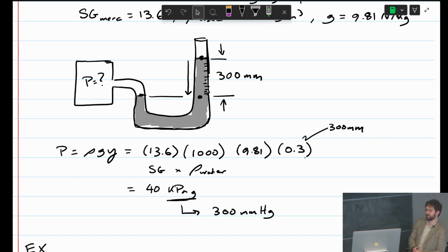Yes, maybe Aaron. Okay, Aaron can go first. Um, so when a fluid's in a cylinder like that, it kind of comes up a little bit at the edge. So if you change the diameter of the tube, would that help? I'm not sure which direction. Yeah, that's a good point. An issue in reading manometers is that you kind of get that. That's actually due to surface tension. So definitely adjusting the tube diameter here so that that's easier to read is something you could do. Did you have another idea?